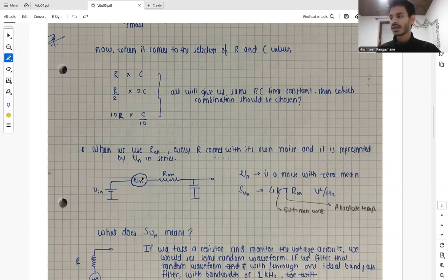So Vn is basically a noise, and the mean value of that noise is zero. The noise is always considered in spectral density. So the spectral density of this noise is nothing but 4 kT times R on. I have talked about these concepts in great detail in the analog IC design playlist, so please refer to that playlist.